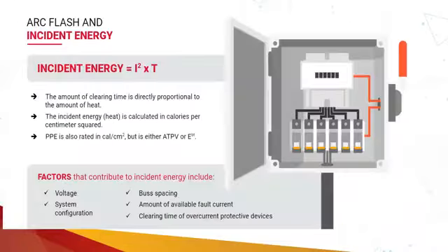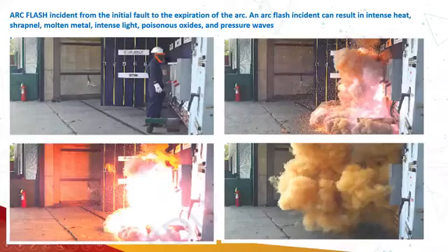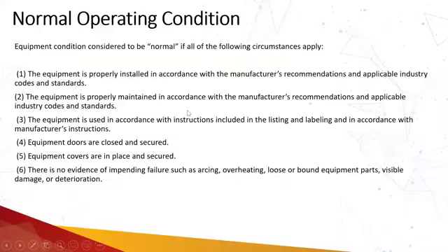Thank you, sir. But what about devices to prevent impending failure in real time? Yes, for example, thermography. We perform it to identify if there is some hotspot, which will indicate that there is overloading.